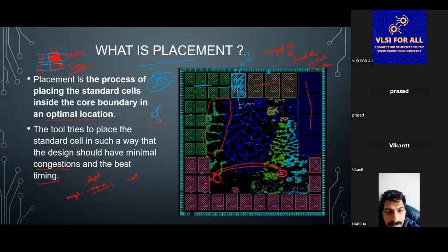If you observe clearly, we will cut the rows around the macros. We will draw the power stripe. The power stripe will connect to the macro power pin, and that power pin will supply the power inside the macro. So it won't get power from the follow pins. We will cut the follow pins, we'll cut the site rows around the macro.